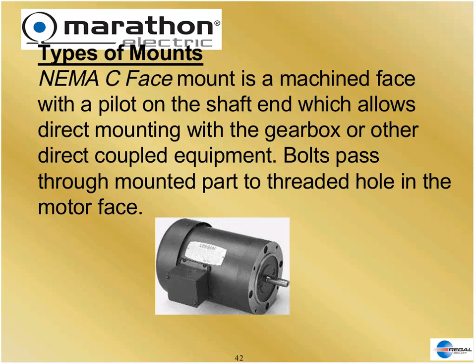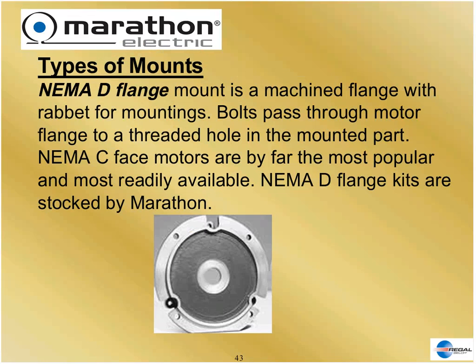Sometimes we don't want to mount the motor by its foot. We want to mount the motor up against a bulkhead or into a gearbox or whatever. So we use a flange mount, this is a typical flange mount. It's called a C-face. It's hard to see, but these holes are tapped, so you can actually bolt this motor right to a wall or to a bulkhead or to a gearbox. And you wouldn't need the foot. You can have the foot, but you wouldn't need it.